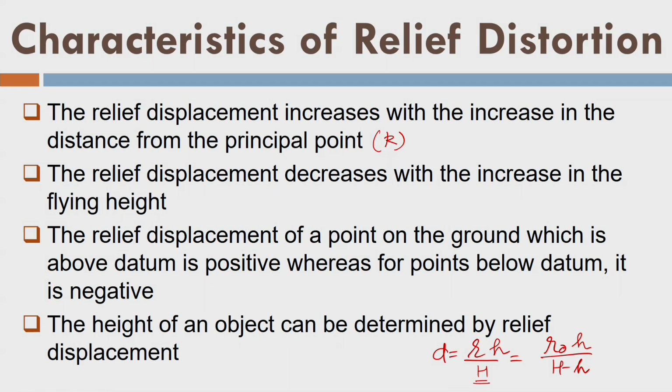And that is the key. If you don't want relief displacement, it is better to increase the flying height. So what will happen in that mission? All the buildings will appear very, very small. But in another sense, relief displacement also gives me some sense of height. So the choice is yours, whether you want to suppress the heights or whether you want to increase the heights represented in the photo. Choice is yours.